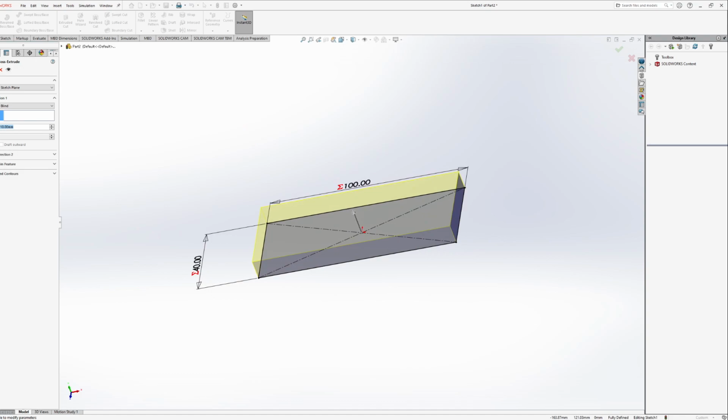Anytime you note that there might be some sort of variable that you would like to integrate with an equation, just slap in an equal sign and see if it works. So I can put equals, it'll allow me to select my global variable a, and then I'm going to multiply it by 3 divided by 2. This is actually a much better example because I'm pretty sure you guys can actually see it this time. And I'll hit millimeters.